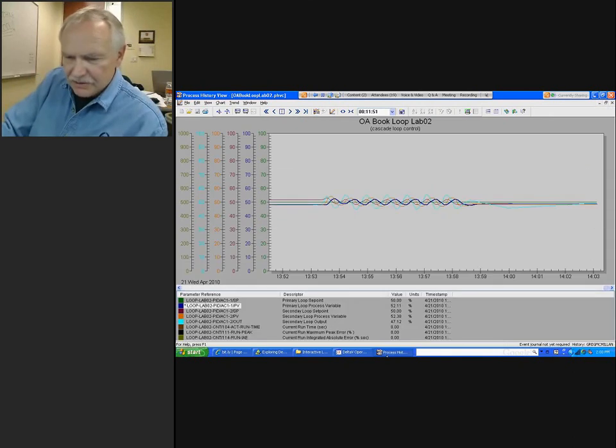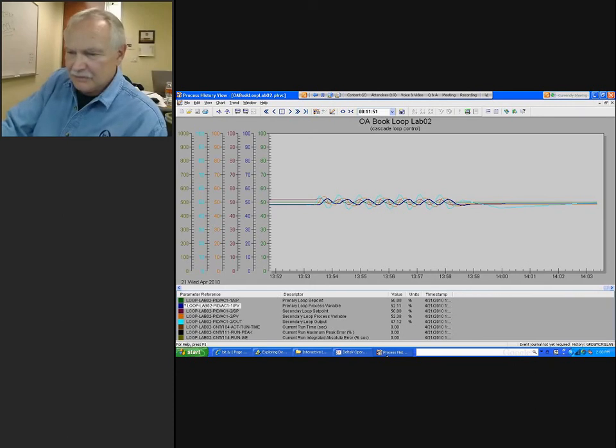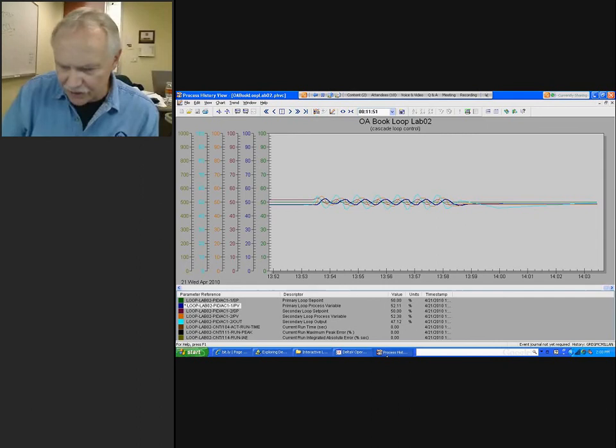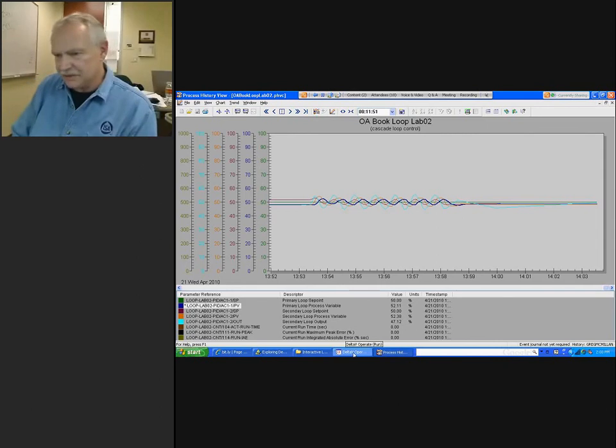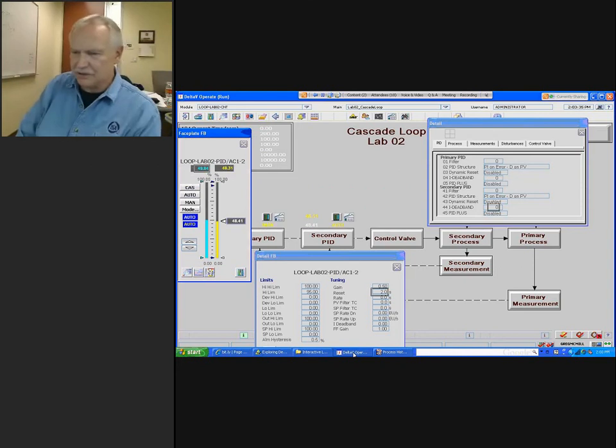All right, well, let's go on to integrating processes, and I know we're running a little short on time. We're going to go over a little bit. Hopefully that's okay. If you have to sign off, basically you've seen the effect of various cases in a self-regulating process. What we're going to show for the integrating process is that deadband in itself, whether you're a single loop, cascade loop, or any type of loop, is going to develop a limit cycle if you have a type of integrating process.